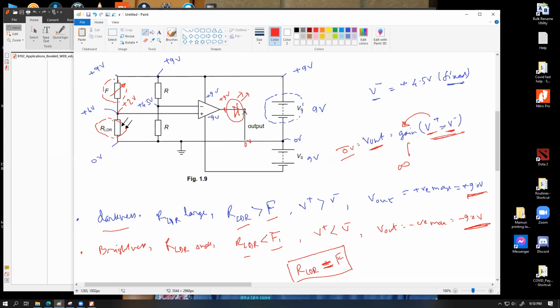But if you connect these things to two physical inputs, then having a steady 0 output is pretty unlikely, which means you are always going to have some difference between them. So in some cases V plus is bigger, or V minus is bigger, so you can have plus or minus 9 volts output. Your outputs will, in most cases, vary between +9 or -9 because it's very unlikely to have these two values be exactly equal for a prolonged, observable duration of time.